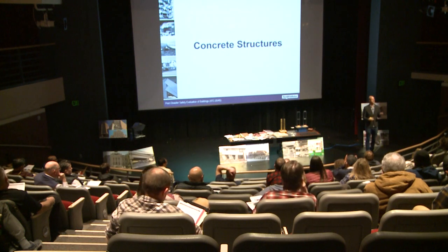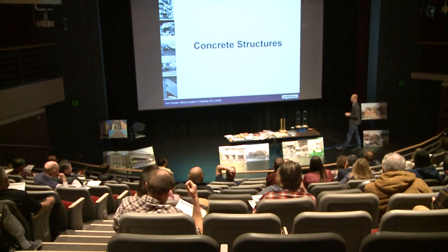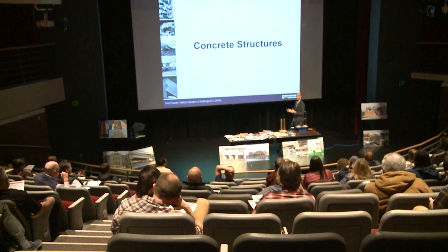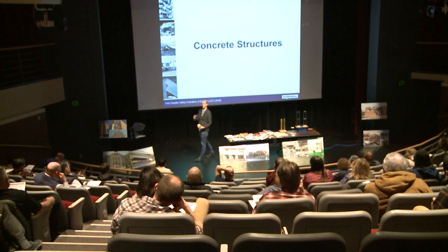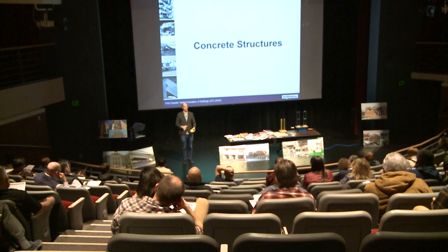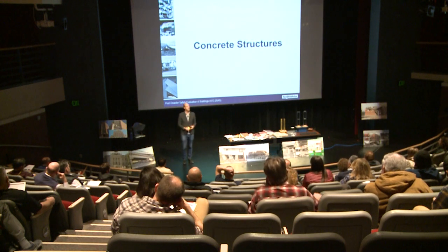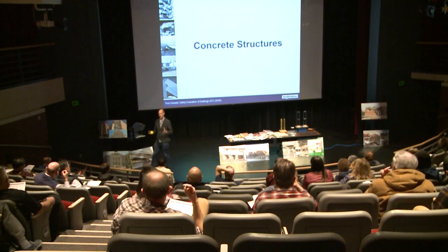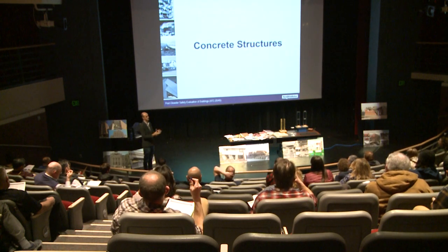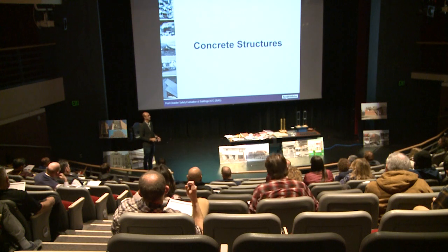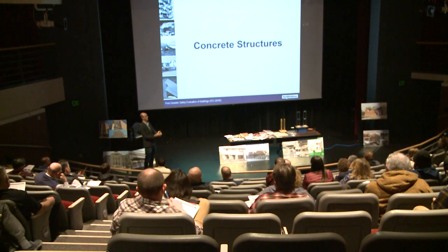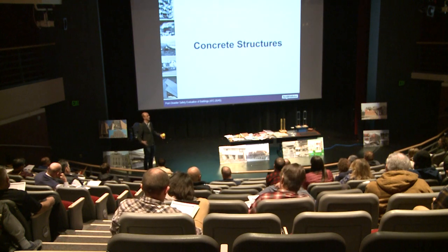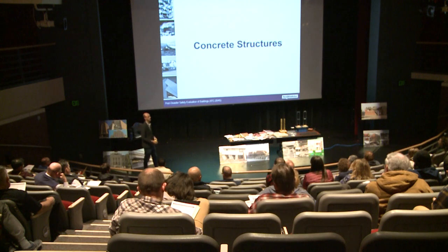So to some degree, some of the examples that we've seen that have vertical distribution of damage are that. The other comment I think that was made was poor design. Well, just from a strictly efficiency standpoint, the ideal would be to design it so that the load and the capacity are equally proportioned such that damage is occurring equally up the height of the building, which is not really practical in many cases. But all that to say, if there's distributed damage, that's probably better than having all the damage concentrated in one spot, because you can spread out the energy dissipation occurring within the material yielding, circling back to that force displacement graph that we talked about earlier.